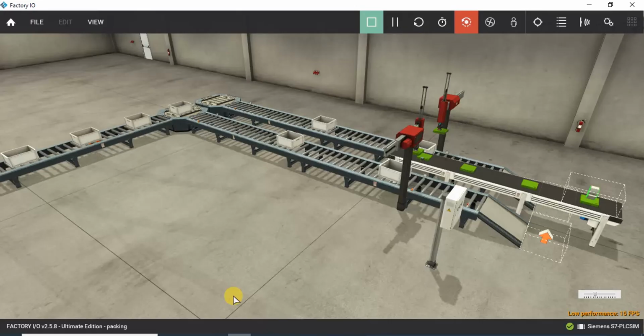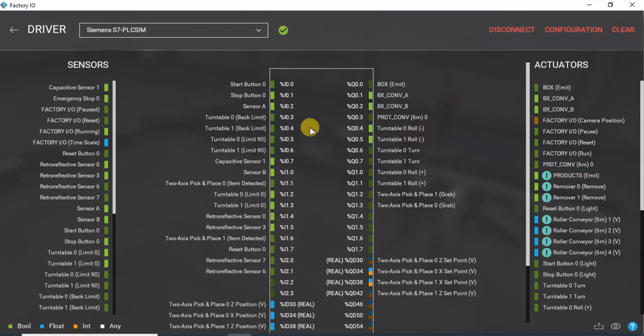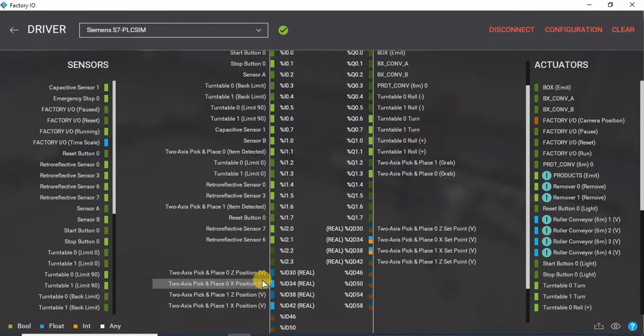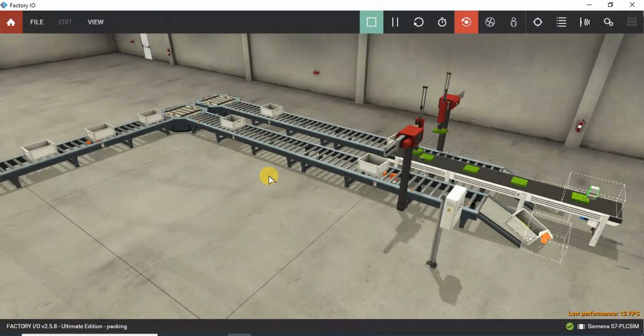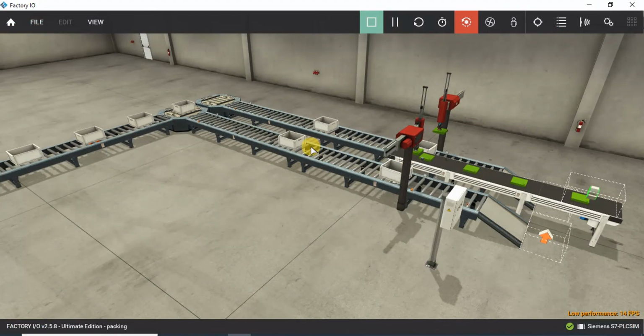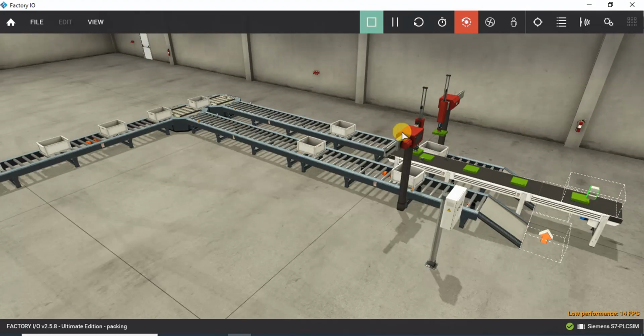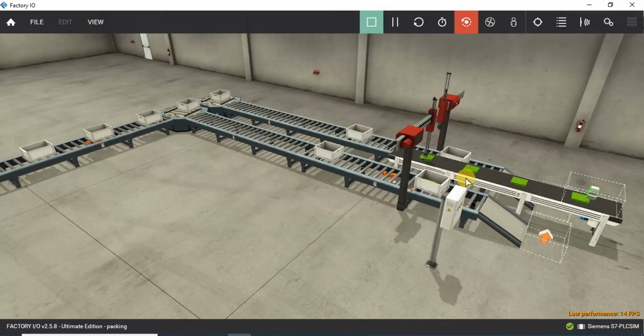And now when we come to our PLC here, you can see all these are inputs. I have quite many. All these are outputs. Those are digital, discrete. Then I have here 4 analog inputs and 4 analog outputs. The analog inputs and outputs, this conveyor, this one and this one and this one, the ones which are working at different speeds, they are analog. Then these pick and place arms are also programmed. The positioning is the analog positioning.